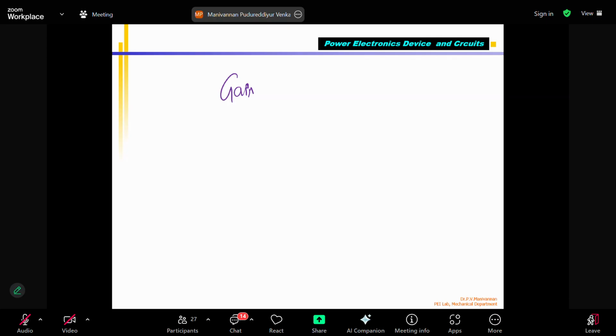But meanwhile, I want to amplify my sensor signal, for example a thermocouple, 0 to 100 millivolts representing 0 to 100 degrees, or a force transducer 0 to 500 millivolts. Generally the sensor gives millivolts representing, for example, 0 to 50 Newton meter, as in a torque or force transducer. Those signals are still millivolts, and if I connect to a transistor, it will load and error will happen. If I use a FET, it doesn't take current but still amplifies and provides a current. Finally, instead of IC, here we get ID, the drain current. So amplification happens without loading effect. That is the main advantage of FET.